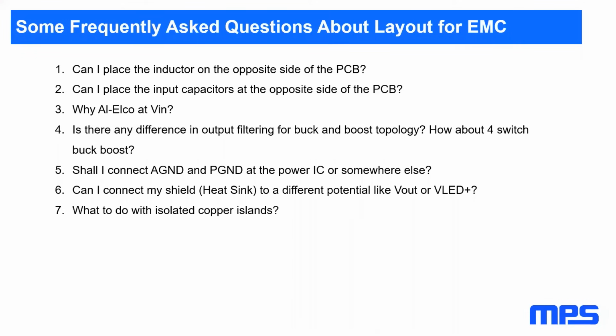What to do with isolated copper islands in my PCB? During the layout process, you should carefully check that whatever copper islands you have are connected through vias to the ground. If this is not possible, better remove the copper.